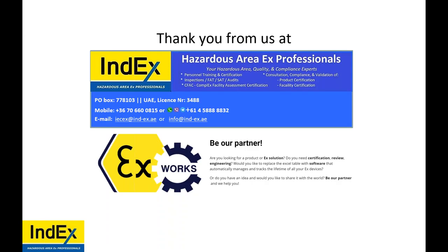So when we talk about anything on UPS, you're talking about the battery transfer switch, you're talking about the phones, you're talking about the fire and gas devices, any of the SIS devices would probably also stay online, also the ventilation fan. But EXE is always a 2C gas group. Primarily what we are talking about right now is EXD equipment. The very first type of EX protection technique to exist was EXD, explosion proof.